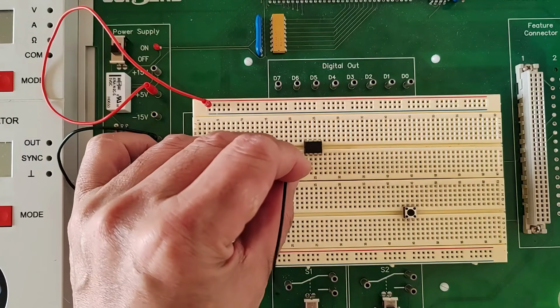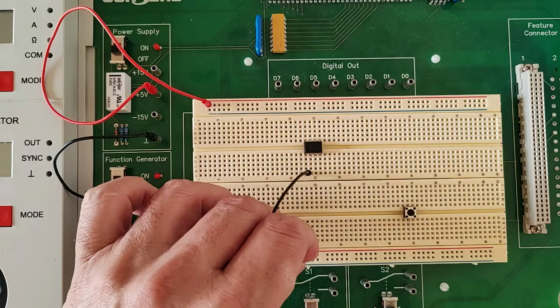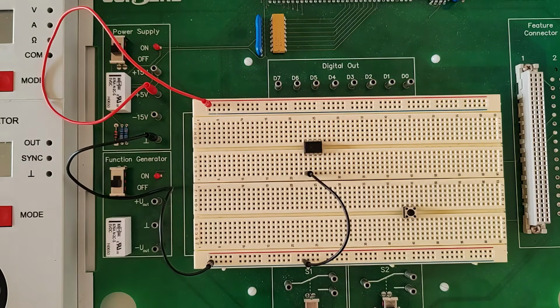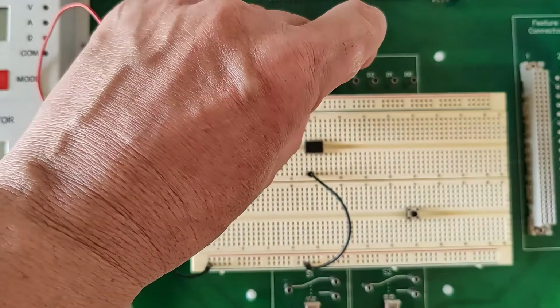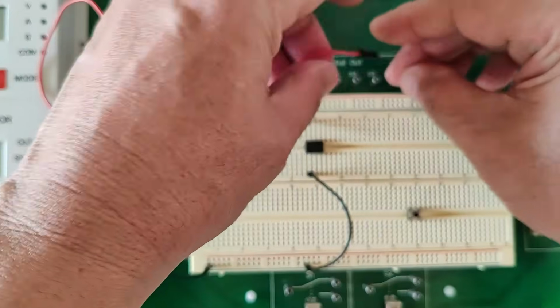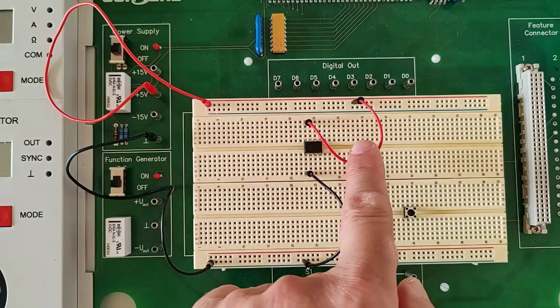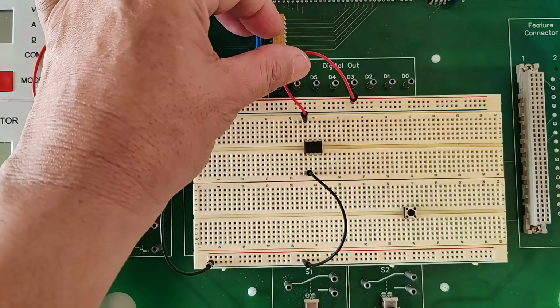Pin 1, ground, will have to be grounded. So let's do that now. It's connected here at the bottom, where the ground wire is connected. And the positive VCC pin 8 will have to be connected to the top red power rail, VCC at the top, as you can see there.